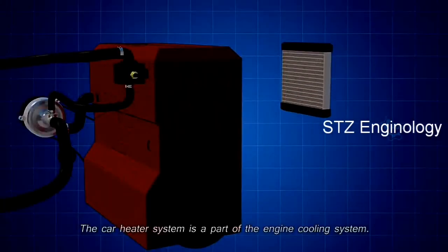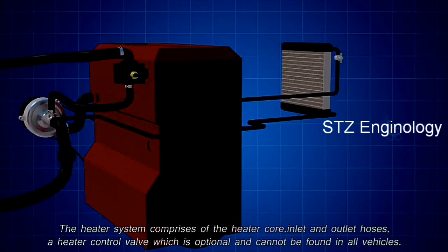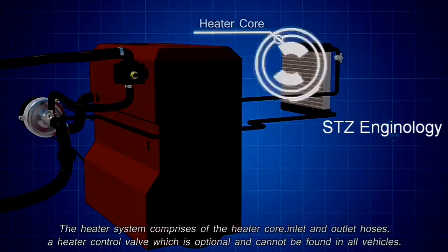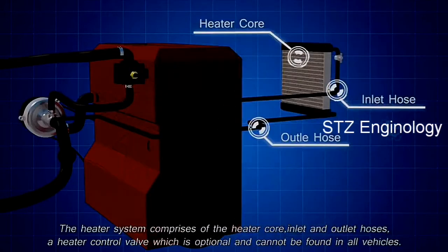The car heater system is a part of the engine cooling system. The heater system comprises the heater core, inlet and outlet hoses, and a heater control valve, which is optional and cannot be found in all vehicles.